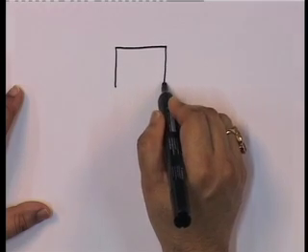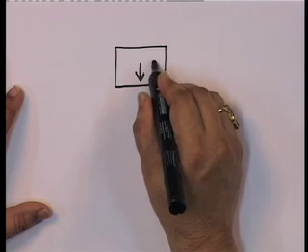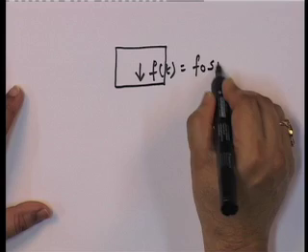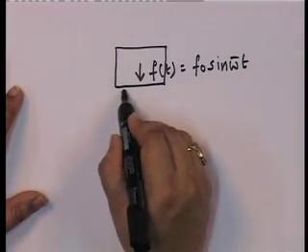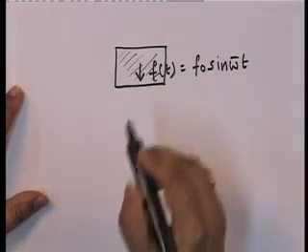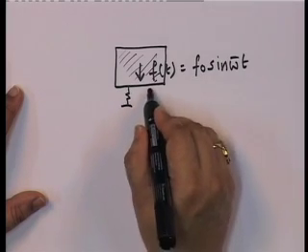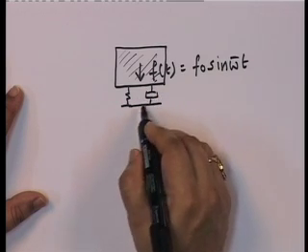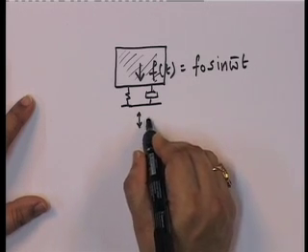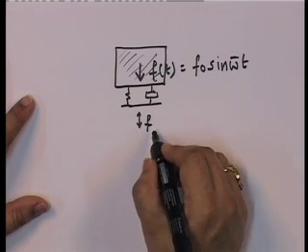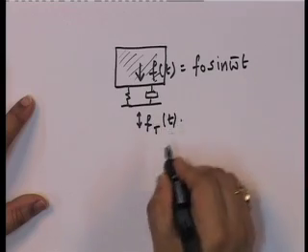That's a simpler problem for us to understand, because for the base isolation problem, I'll have to start defining some new parameters. So, before I do that, I will look at the force transmissibility problem. I have an equipment which is transmitting a force F of t equal to F0 sin omega bar t. This rigid machine is connected to the floor through some spring and dashpot system, and I want to figure out what this transmitted force is equal to.